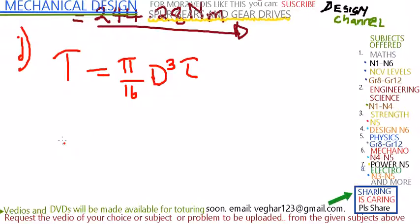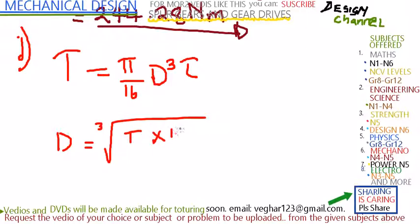Changing this formula, we have something like D equals the cube root of T multiplied by 16 divided by shear stress multiplied by pi. So you can derive this equation, or you can substitute directly from here.